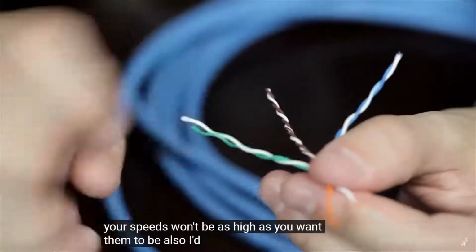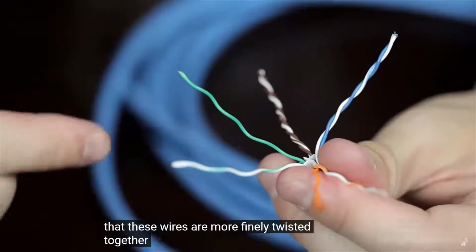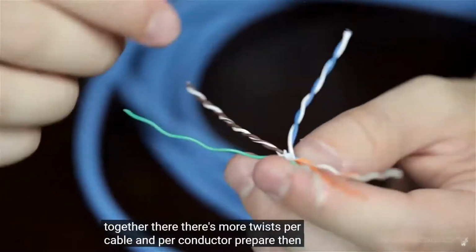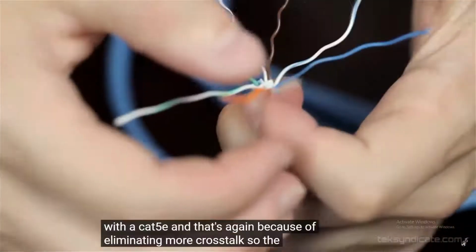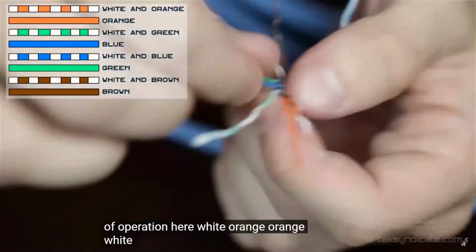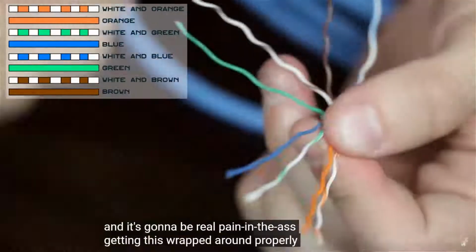Also, I'd like to point out that these wires are more finely twisted together. There's more twists per cable and per conductor per pair than with the Cat5e, and that's again because of eliminating more crosstalk. So the order of operation here is white, orange, orange, white, green, blue, and it's going to be a real pain in the ass getting this wrapped around properly, but we're going to put it over there.